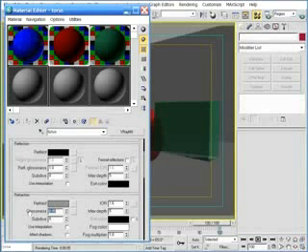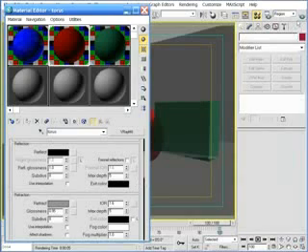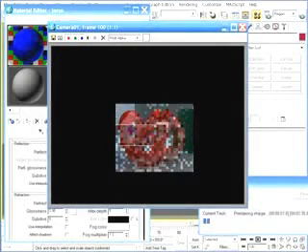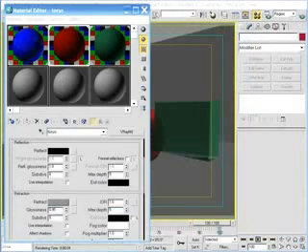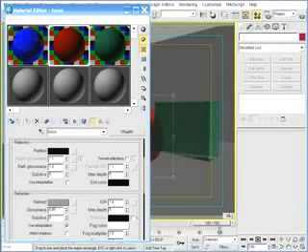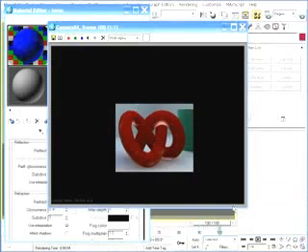So I'm going to enable glossy refractions on the torus, which will simply make the light scatter as it goes through the object, much like it does with translucency. I'll start the rendering, but notice how slow it goes once it gets past the GI calculations. I can significantly reduce the rendering time by enabling use interpolation, which is this option here. But using interpolation here is not as easy as just enabling an option.